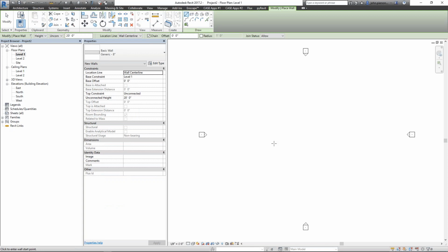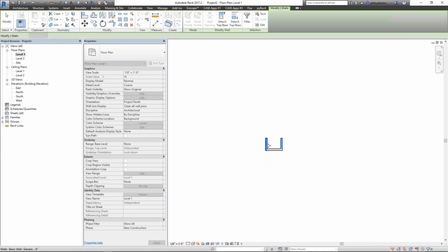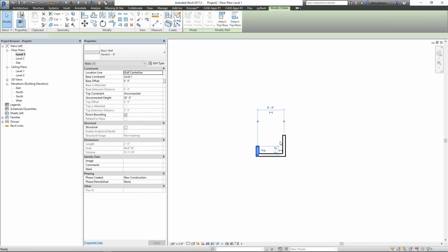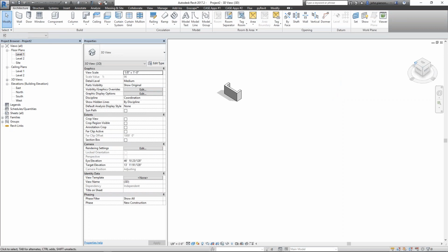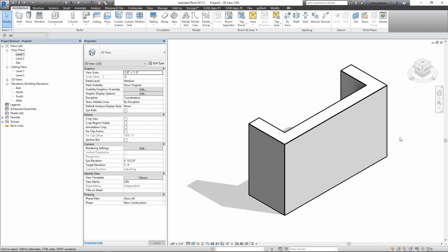You could use the unfold package, unfold it, and it labels the panels 01, 02, 03, 04, and flattens them out. You could throw it out to CAD if you wanted to, then load that in the model, and it already documents all the panels for you. Then you send that to a CNC or, in your case, a laser cutter, and you cut out those panels, and they're numbered. They show up on the site, and they put it together like Legos. So these complex forms are complex, but they're not impossible to build. You just have to be smart about it.